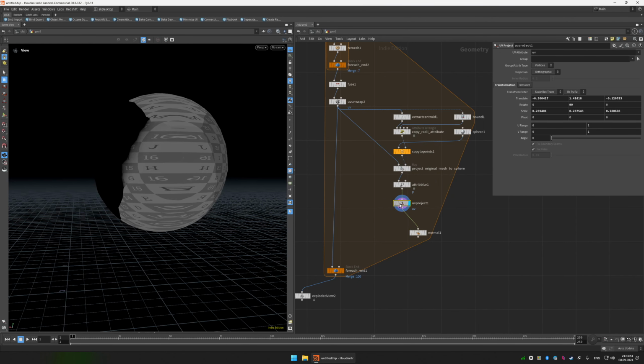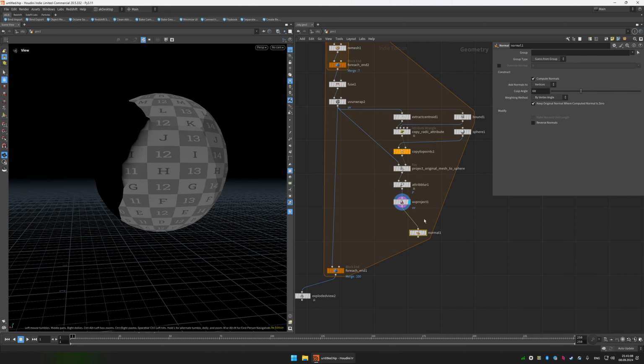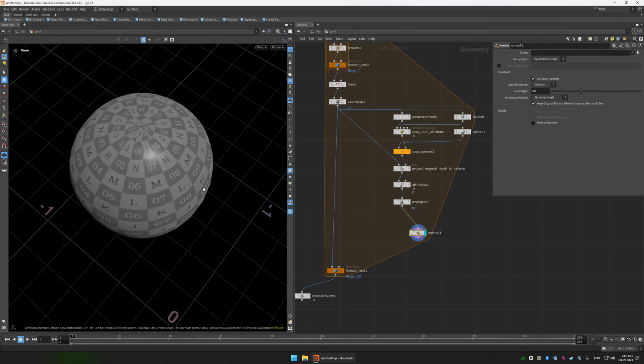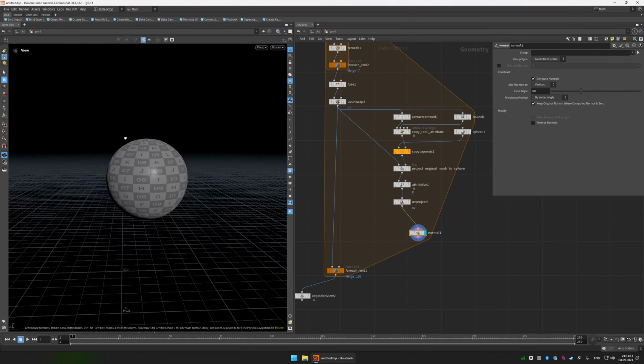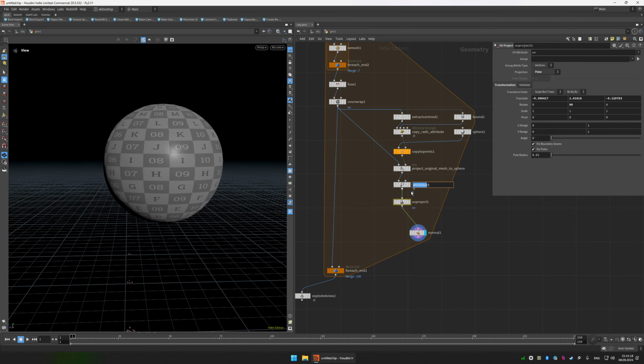We can set this to default, so I'm gonna just press Ctrl and middle mouse button. Okay, I'm gonna leave this at 90, and then here I'm just gonna select the polar UVs, and as you can see, it somewhat creates nice UVs. Of course here we got pinching, but that's not a big deal. It's still a lot better than what we had before.